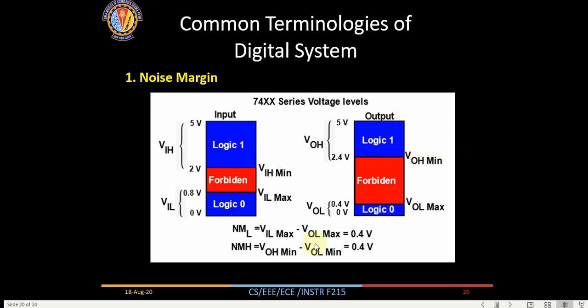Now, why I call this noise margin is, this output I write to another gate. It could be within that chip, or on the PCB on a different chip. When I transmit, that wire will pick up some noise. So how much noise can my circuit tolerate? It is 0.4 volt, minimum. So maximum another 0.4 volt of noise can get added, and at the next stage there will be no error induced. Is it clear now? That is how these noise margins are defined.